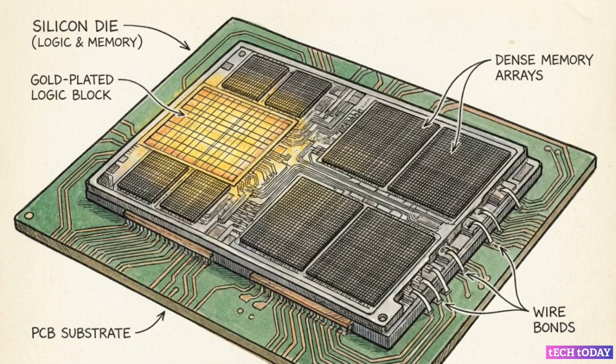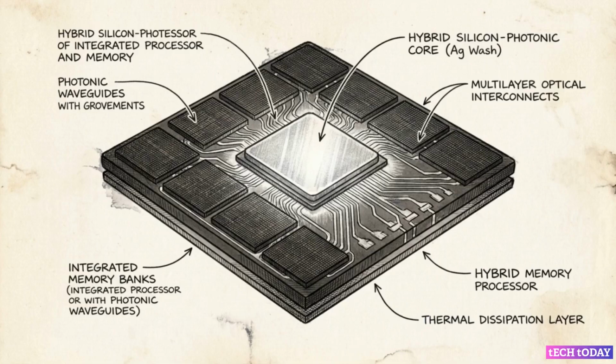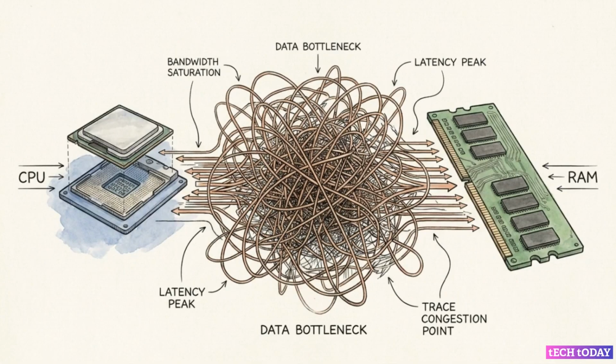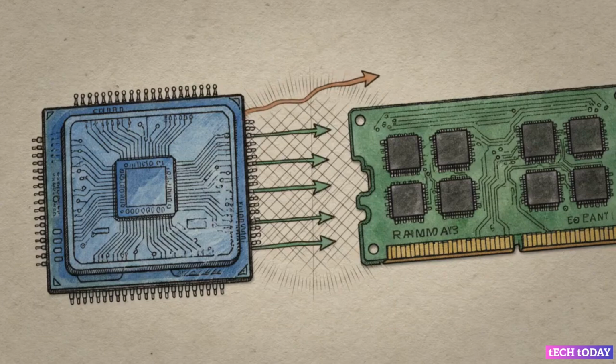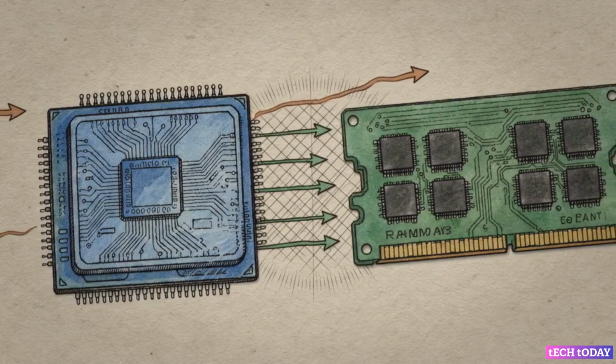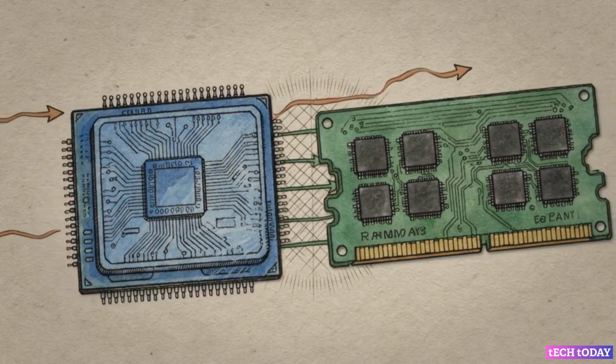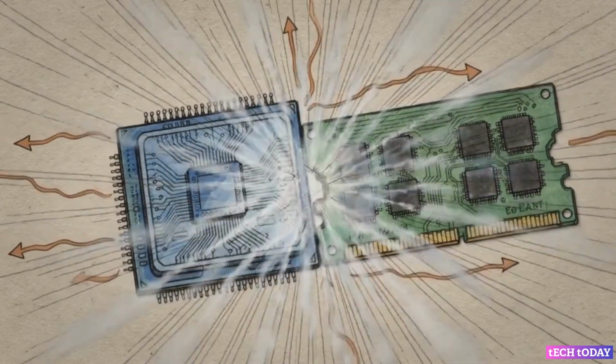To prevent this corruption, DDR5 includes error-correcting code directly on the silicon die to catch internal manufacturing faults. However, the future lies in processing-in-memory, or PIM, which places the logic compute cores directly inside the RAM itself. The memory wall cannot be defeated by simply forcing higher clock speeds over copper wire. To eliminate the latency bottleneck, the next generation of computing relies on destroying the physical distance between data storage and processing.